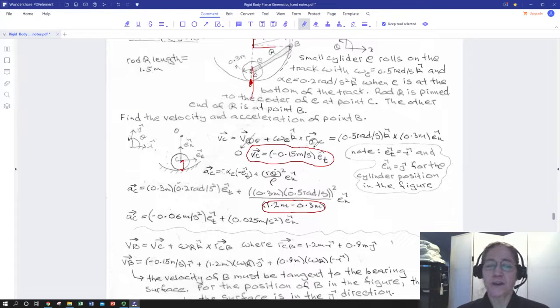Likewise with my acceleration, we're going to have r times alpha instead of omega, because we're looking at acceleration. It's a center point, it's rectilinear motion, and we're going to have that same negative tangential hat because we're basing it on that same cross product. You could also think of it as this negative sign following your unit vector, and you're just taking the second time derivative of your angular position to get alpha. So we're going to have a negative sign on that first part of a_C.